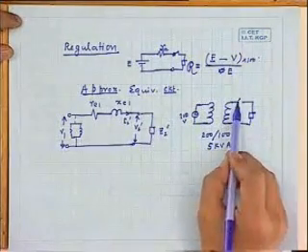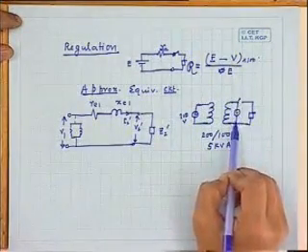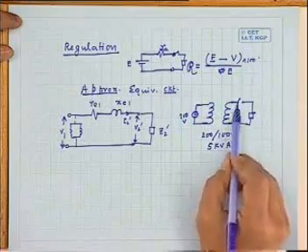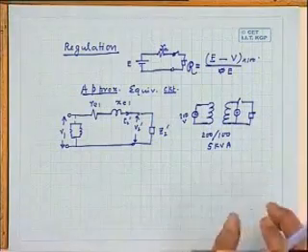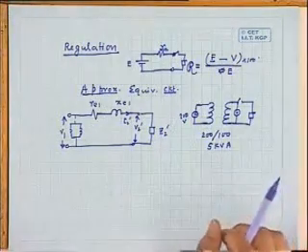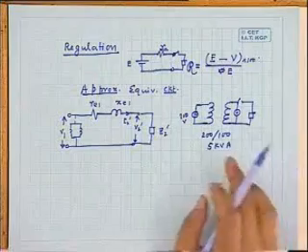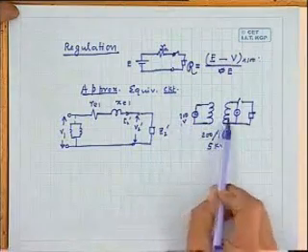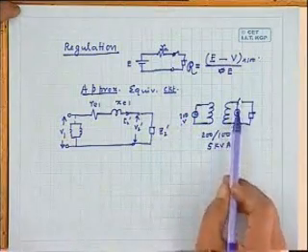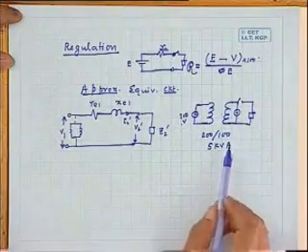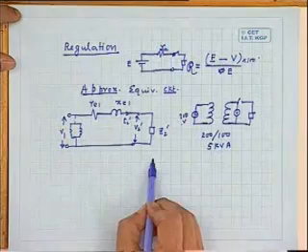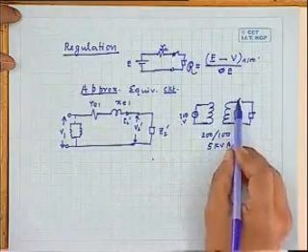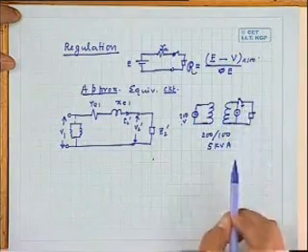And I will connect a load here on the secondary side. First I will measure the voltage available here with this switch open. See, I am telling how you will measure the regulation. Let us not go into any mathematics. So the transformer is given, I will give 200 volt and I will get some 100 volt here under no load condition. So that voltage I will record.